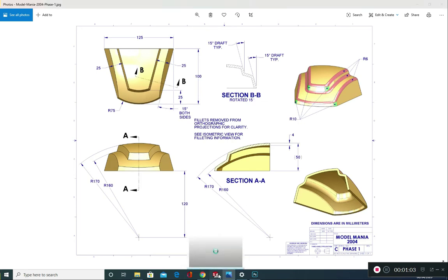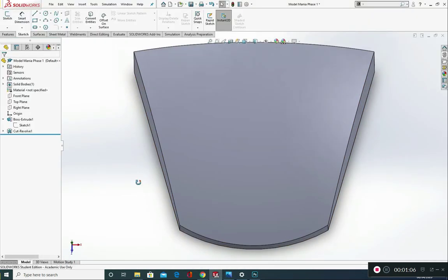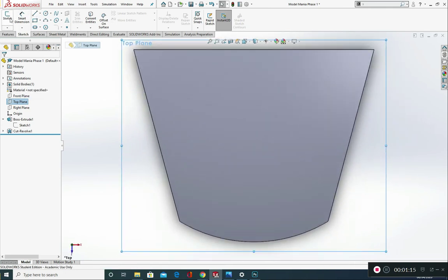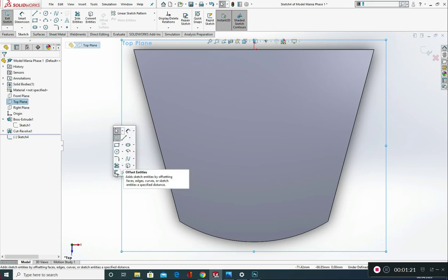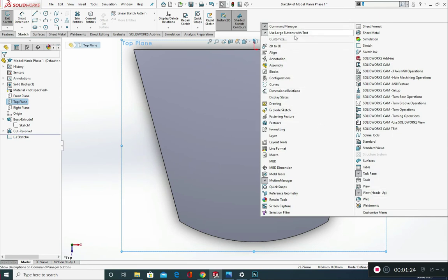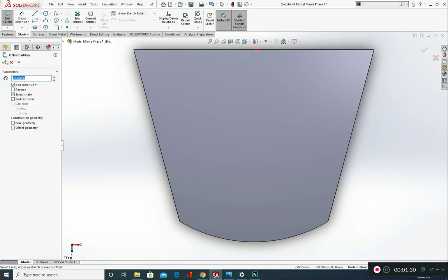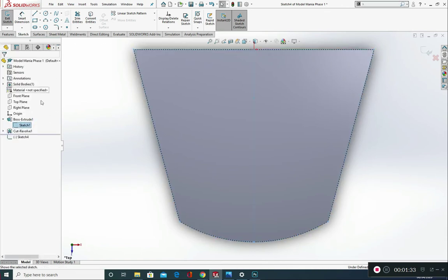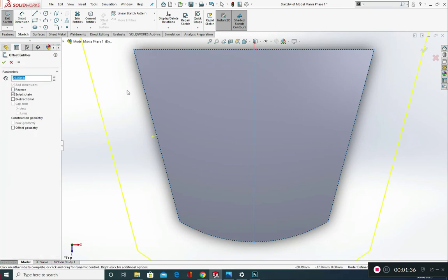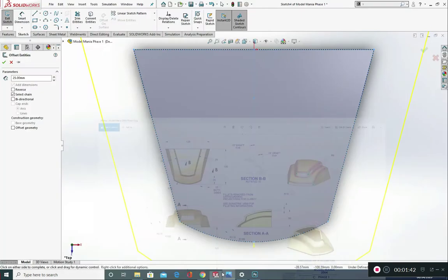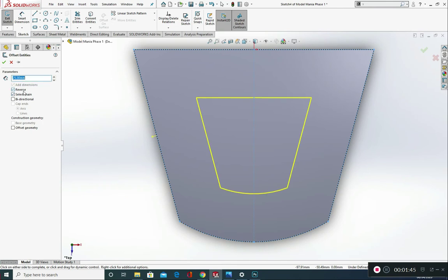So I would go into Solidworks, I would go to my top view, normal 2, produce a sketch, press my S key, and this is where I keep my offset. Remember, you can get that from the customize menu if you want to, underneath customize. So I'm going to press my S key, offset. Where's my sketch? There. So S key, offset. I'm going to put in the value of 25, but it is inwards, so reverse the direction, and then green tick.